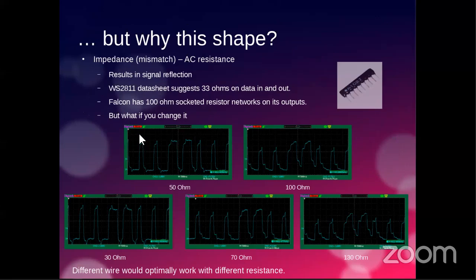There it is. So yeah, at 30 ohm, a much cleaner signal. None of the reflections that you see at the 100 ohm here. So much better. Are these resistors just relevant to the controller itself, or do they have any impact on the differential receivers? No, they do not. The differential receivers do not go through these resistor networks.